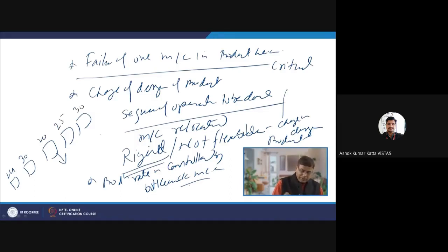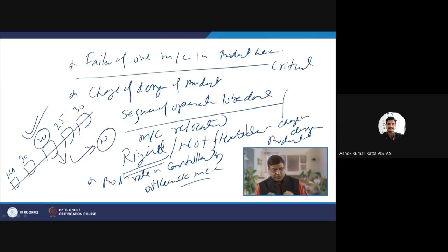So the maximum production rate which is possible through this kind of product line is 20 only. This will be dictating the maximum production rate which can be realized, and this will be the bottleneck station here, because others can do more but they will not be able to, otherwise it will be holding up the production at this stage. So this will be governing the rate of production.